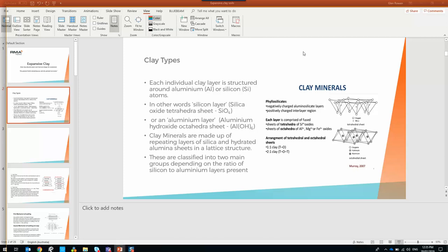So it's also the depth of the clay layers. If you've got a shallow bit of clay over rock, it won't swell as much as if you've got deep-seated clay, because that depends on the depth of moisture change. Typically in Toowoomba, our range of moisture content, what is it these days, 1.8 still, Dean? 1.82 metres, and the further west you go, it can be up to 4 metres deep when you get out in the bad drought areas.